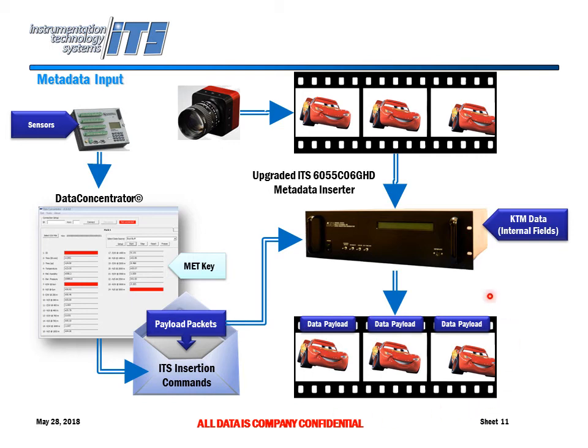So your output video then is the same video you brought in, uncompressed, unmodified in the image area, but up in the data space, and the blank data space specifically, we put KLV packets, possibly 2 additional packets from the microsecond timestamp. So you can have 1 microsecond timestamp or up to 2 KLV packets. So you have 3 packets up there, and that data has all been captured and synchronized with the video.